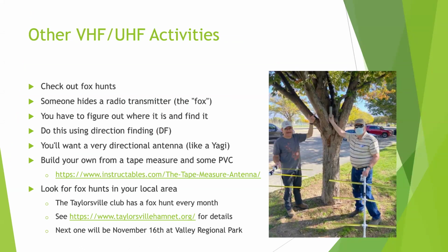Other activities, you can check out fox hunts. I know Taylorsville does a fox hunt every month, the second Saturday of every month, starting at noon. Basically, the idea is somebody hides a radio transmitter somewhere and you have to figure out where it is and go find it. You do that with direction finding techniques. So you'll want a directional antenna like a Yagi. A lot of people have a Yagi antenna that they've made with a tape measure and some PVC. It's relatively easy to make one for 2 meters or for 70 centimeters. There's instructions on this site right here on how to do it.